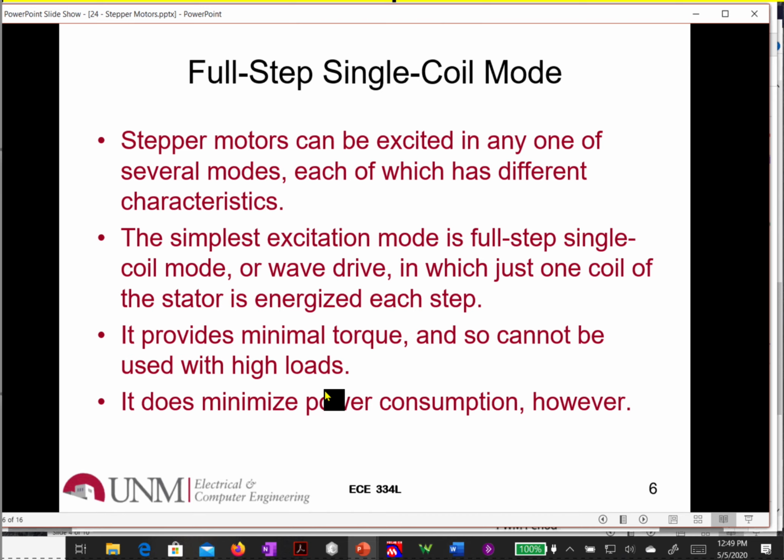So somewhere or other I need to have some magnetism in this system to allow it to move. And if I have slip rings and I have windings on the armature as well, then I can have both. I can have non-magnetic components, but I generate my magnetic field using current through the windings, and so I complicate my design, but I have slip rings or brushes now.